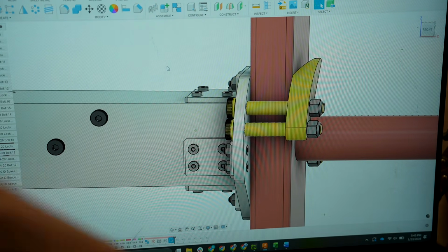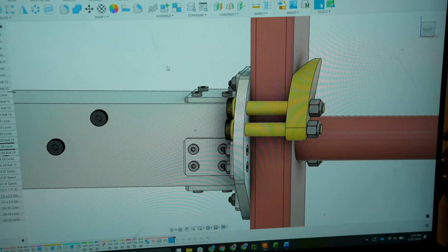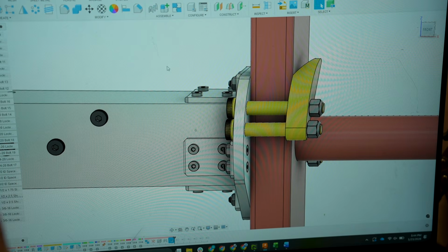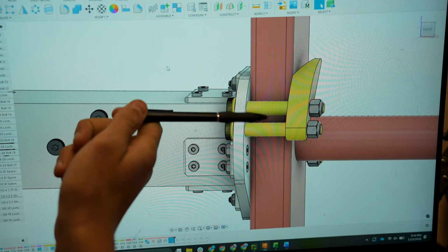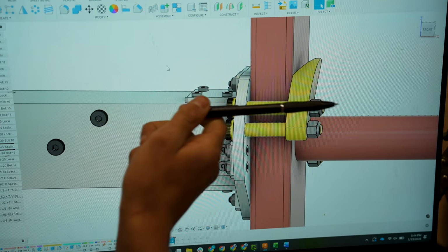What do you think? Usually, you can assume that for 2 bolts, as long as the shear is not directly parallel to them, which it's not. So you'd assume that the aluminum hook shifts such that both of them are taking some of the shear. Although I assume you would be able to do equal depending on where the shear is applied. Yeah. So we'll take the conservative case and do shear on this one, and that they're both resisting the moment.